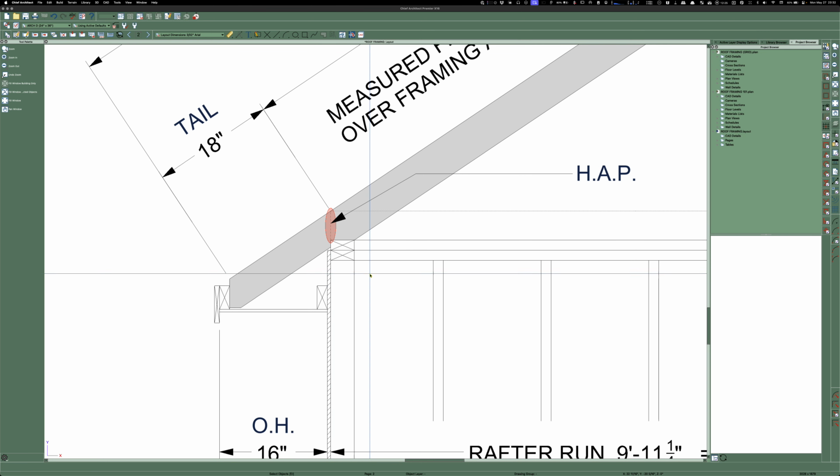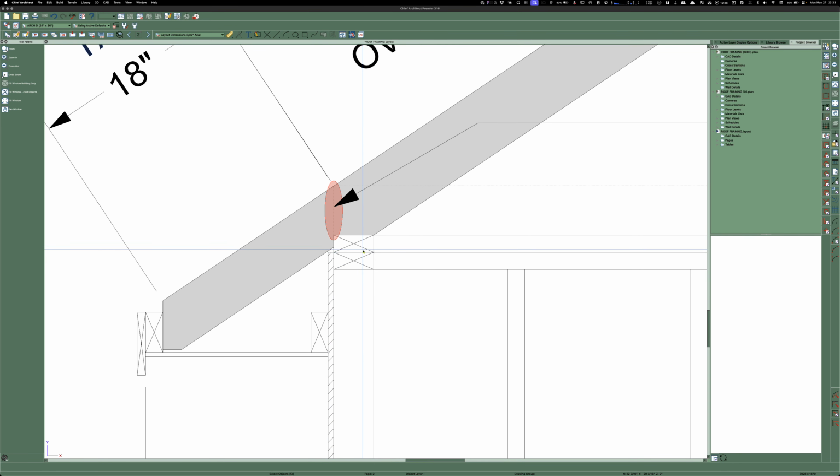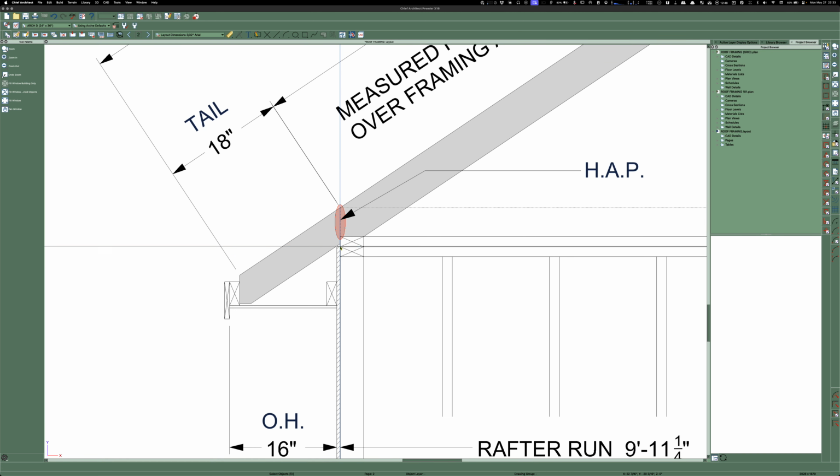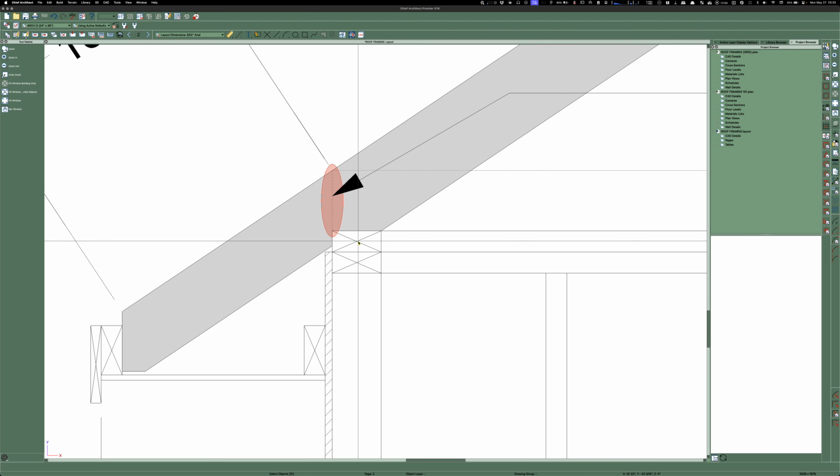And so when we build walls up here, we have them squared on the floor, because we're on crawl spaces, so the floor is pretty level. And then we sheet them while they're laying down, and then we stand them up. And we've always squared the walls, and then you pull the sheeting all the way up to the top of the double plate, and you nail it all on. Well, I started thinking about this just yesterday, and the double plate doesn't do anything for a shear wall.